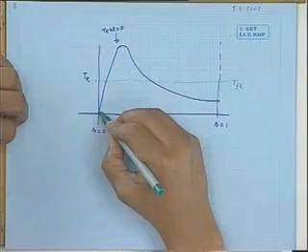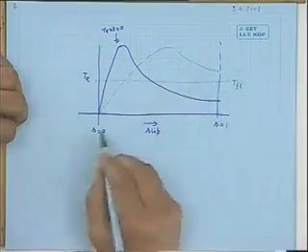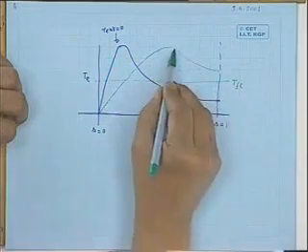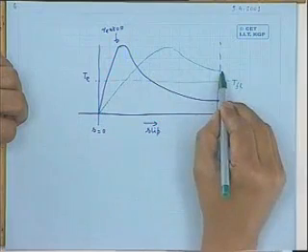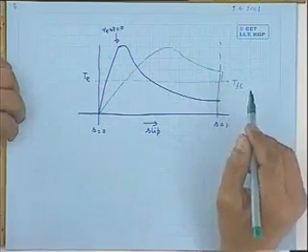So, in such cases, what will you do now? Instead of keeping the rotor shorted, you connect some external resistance in the rotor, equal values in all the phases. That's why I showed the gang resistance as external. So equal values you connect, like a 40 ohm gang rheostat, three you use, connect them. And you modify the torque slip curve such that suppose this value you choose. Some R external you connect so that the torque slip characteristics is shifted towards the right in this fashion, such that the starting torque now will be this much, full load torque is this much, the machine will start.